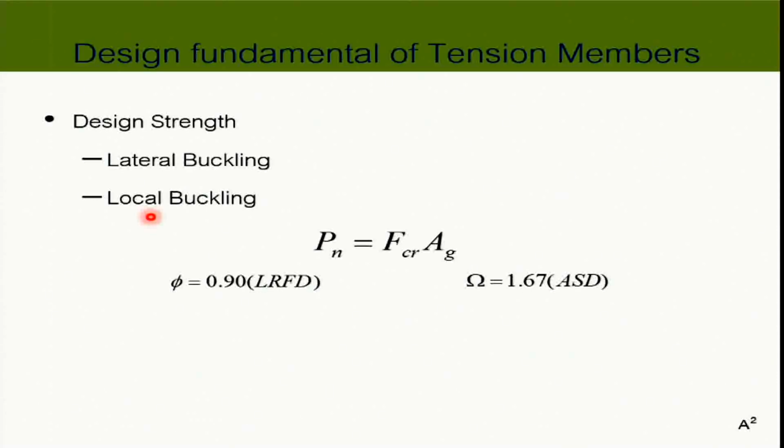And that is why we are not going to use a column made entirely of steel, right? Because it's going to be heavy and inefficient. This is the main reason why we use shapes such as H, I, C, because we utilize the strength. We don't need a lot of weight, because that much will be sufficient.